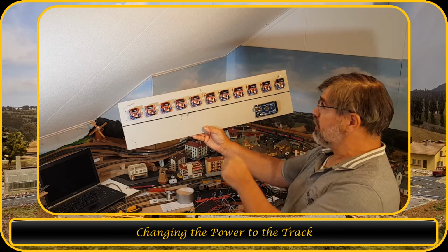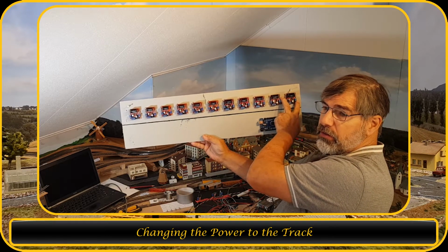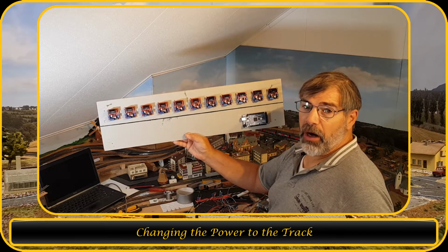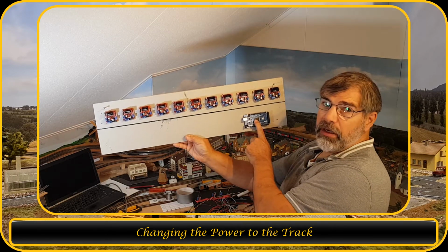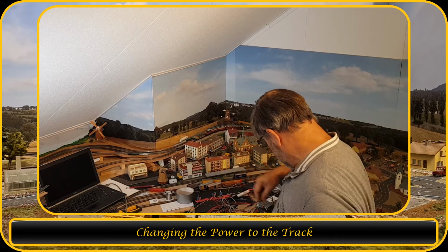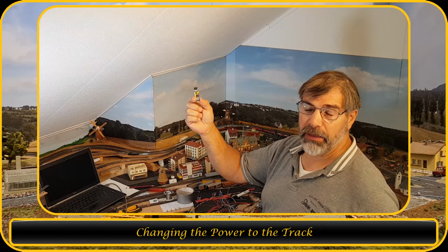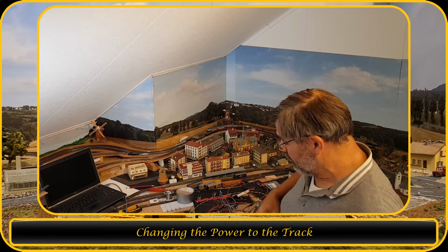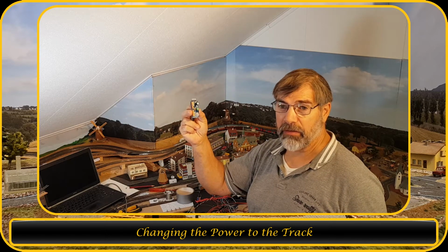So what I'm gonna do is I'm gonna use motor drivers like this, and each motor driver has 2 outputs, so I can control 2 tracks per motor driver to put power on it and also control it individually. I'm gonna control it with an Arduino Mega, and in between the Arduino Mega I'm gonna use the input-output to control the forward and backward motion of the train and to enable that there is power on the track, and I'm gonna use this one to control the speed on each section.